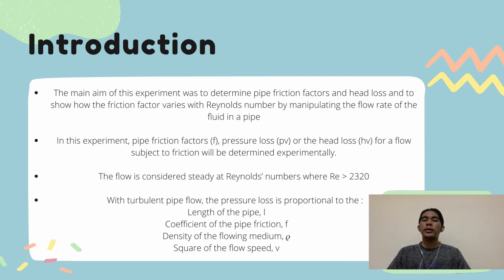Today I will present the introduction of this experiment. This experiment is about the coefficient factor, or what we can know as the friction factor. The main aim of this experiment was to determine the pipe friction factor and head loss, and to show how the friction factor varies with Reynolds numbers by manipulating the flow rate of the fluid in the pipe.